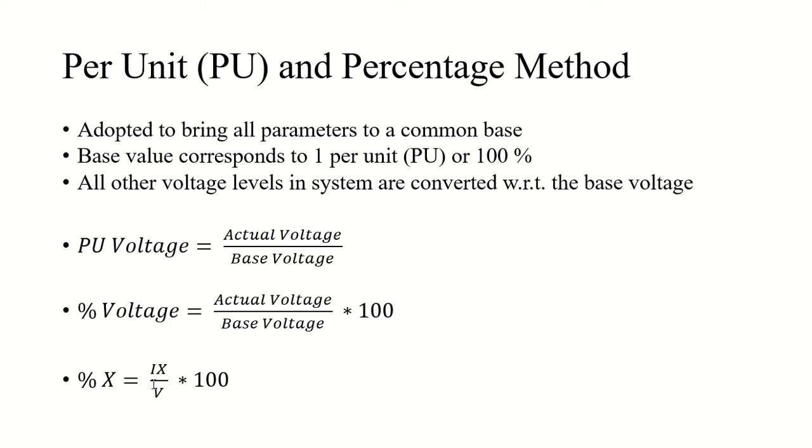What is the reason behind finding this percentage reactance? Not only is it helpful in short circuit calculations, but it also indicates how much total voltage is dropped in the inductance when the full load current is flowing in your circuit. So that is your percentage reactance.